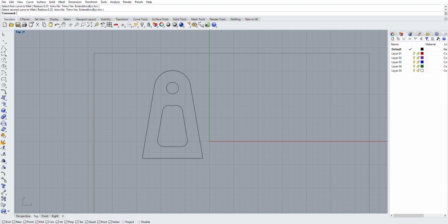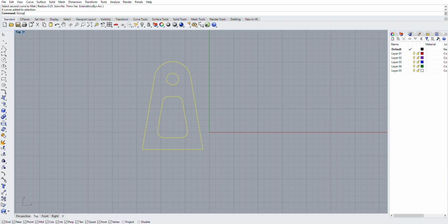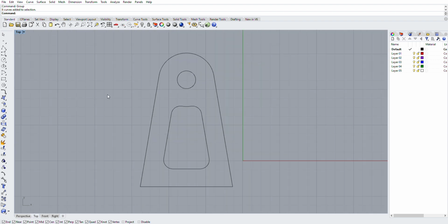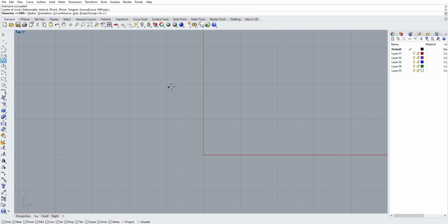Imagine this is something that would take forever on a grinder or a mill or whatever. We can program these tabs in 2 minutes flat. And we can shape them to whatever you want. It doesn't have to be centered. You can put that line anywhere you want. And I'll show you some template stuff later on here.